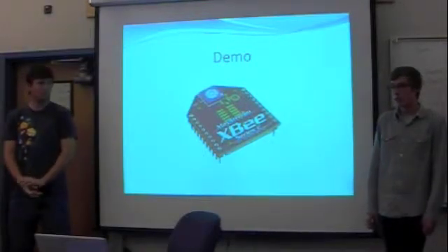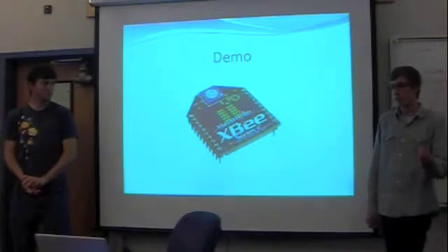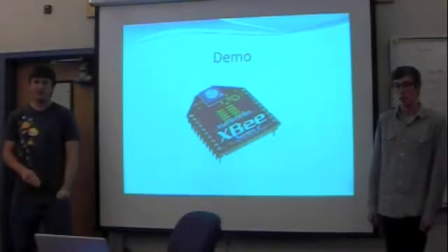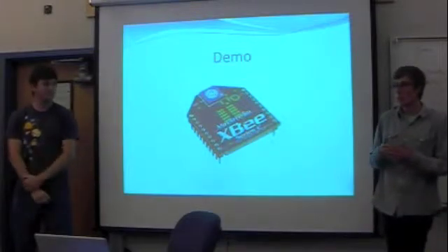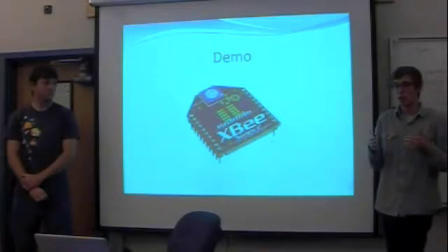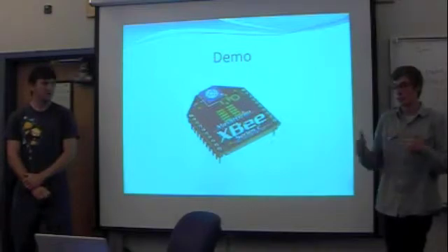The XBee setup works just by plugging it in. It works as a UART, just as you'd expect. The only thing that we ran into with testing was that if you sent messages too fast, the UART couldn't keep up with sending all your messages on top of each other, or it wouldn't receive them on the other side.